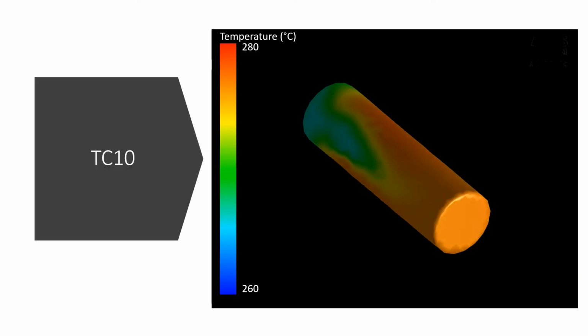The following animation shows thermocouple 10 within the reactor. This thermocouple is used to gather data for controller number 4 so that it can base its decisions on how to alter the mass flow rate of the catalyst into zone 3 of the reactor. As can be seen here, the turbulent flow around this involves creating a high temperature gradient throughout the length of the thermocouple, and this results in a very different moving time average across just several milliseconds of flow time. Because of this, the controller has to respond quite rapidly and with much more gain than the other 4 controllers